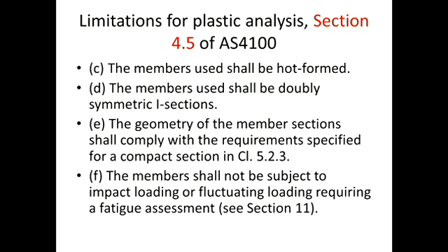The other limitation as well is for us to have doubly symmetrical I sections. So the standard is limiting us to just I sections for plastic design, and the sections also have to be compact. And if we look at the load, if we have any part of the structure which is subjected to impact loading or to fluctuating loading, where fatigue assessment is required, it also means that we can no longer use plastic design.